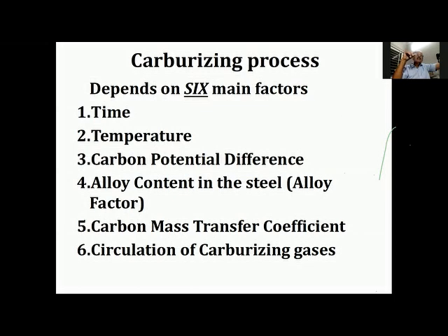The depth of penetration of the carbon, or the carburized case achieved, is proportional to the square root of time. So it plays a law of diminishing returns. Whereas, it is also very easy to control time.